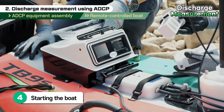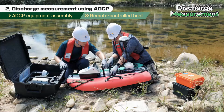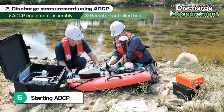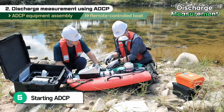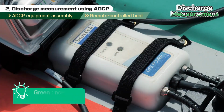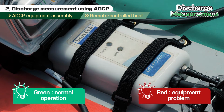When turning on the power, you will see the on light and remaining battery charge. When pressing the power button of the communication box to turn the ADCP on, the light comes on at the top of the communication box. After connecting the communication box and touching the top of the battery with a magnetic stick, the side will light up. The green light indicates normal operation of the boat and communication box. If the red light turns on, it is a signal that there is something wrong with the equipment. Thus, the equipment should be checked again.